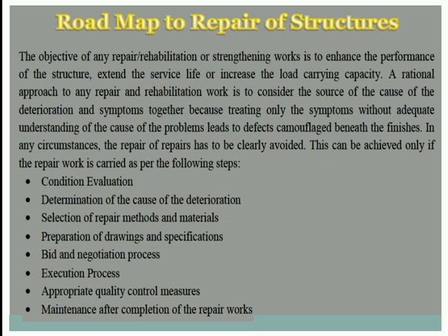It is basically with reference to the leakage in the slabs. The pore or the line through which the water leaks inside the slab has to be properly identified, so that the crack can be easily repaired. Then further, there are different methods of repair available. The method of repair has to be selected very wisely, else the repair work will be uneconomical. Further, the drawings or the specifications required to be executed during the repair have to be framed very properly.